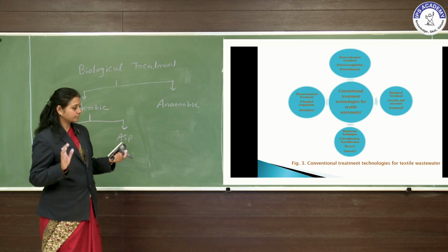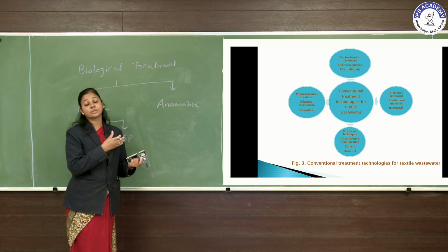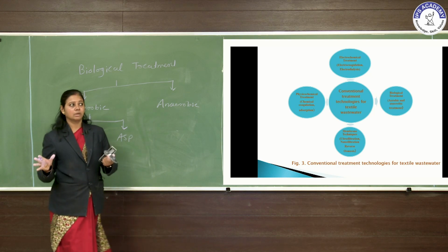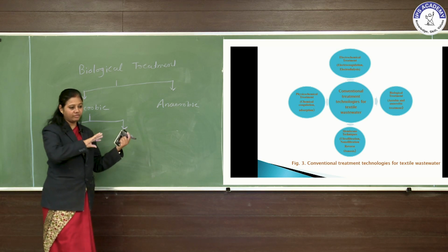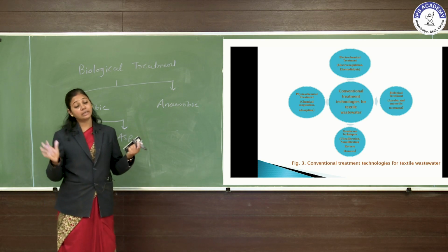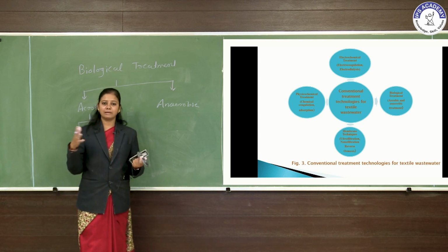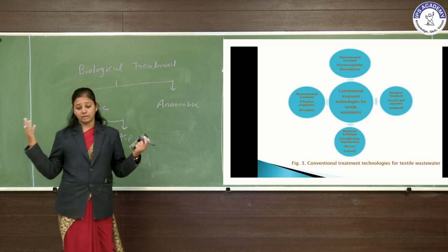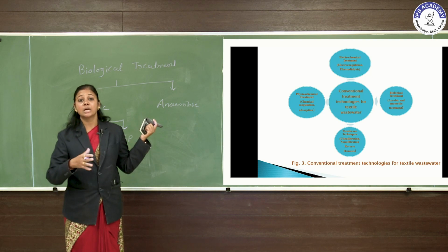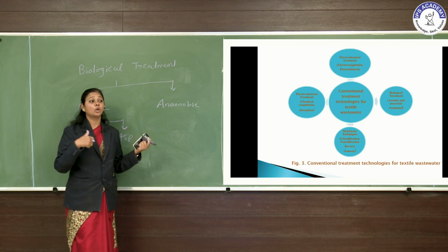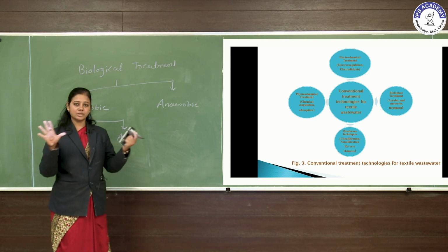Okay, now actually the major drawback of this system is the large retention time. It is not like the wastewater will be treated within a day. It will take about weeks to treat that wastewater. So it is a critical process. A lot of area is required for this aerobic treatment. At the same time it requires skilled supervision. It requires a lot of time. It requires a lot of energy. So this is a very clumsy process right now.